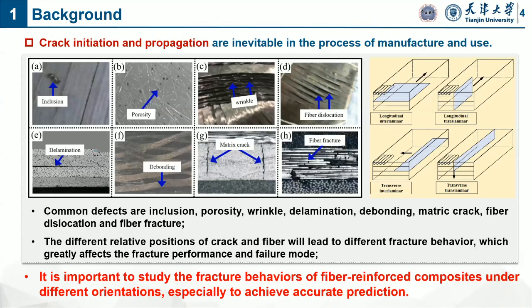Crack initiation and propagation are inevitable in the process of manufacture and application. Common defects are inclusion, porosity, delamination, debonding, matrix crack, fiber dislocation, and fiber fracture.